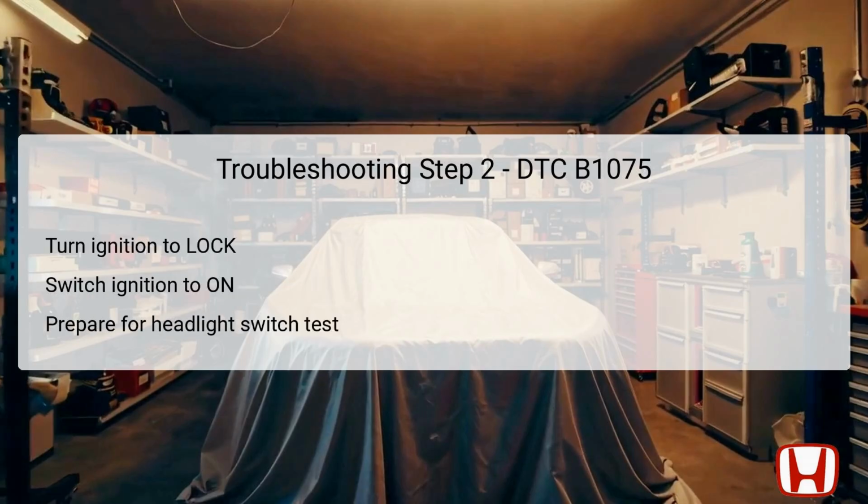Following the clearing of DTCs, the next step requires turning the ignition switch to the lock position and then back to the on position. This action effectively resets the vehicle's electronic systems and prepares them for a thorough check. By turning the ignition to on, you're enabling the vehicle's electrical system, allowing for various tests. It's crucial to follow this sequence accurately to ensure that all electronic systems, including the headlight circuit, are primed for testing. This step does not directly diagnose the problem, but sets the stage by making sure the vehicle is in the right state for further diagnostics.